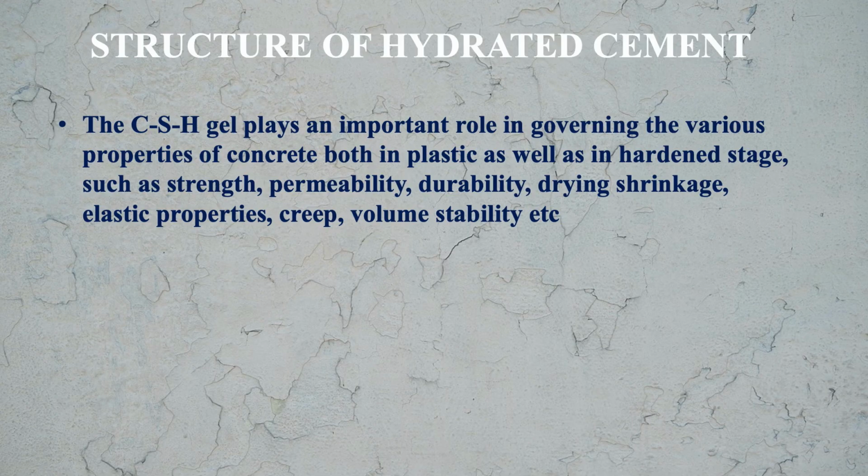The CSH gel plays an important role in governing the various properties of concrete, both in the plastic as well as in the hardened stage, such as strength, permeability, durability, drying shrinkage, elastic properties, creep, volume stability, etc. So these all are governed by the CSH gel.